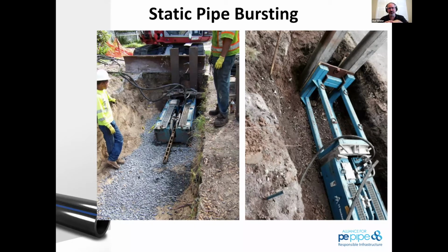It allows the crews to be able to remove all the tooling that's necessary, cutter attachments. So in static pipe bursting, you can put a whole series of different cutters, splitters, or other things in order to be able to remove it.